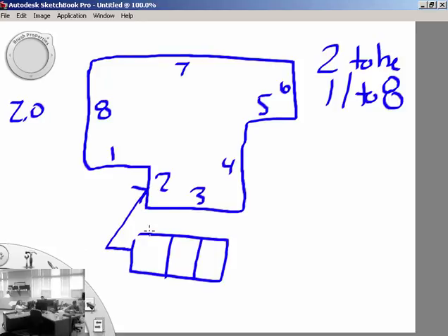Okay, so walk me through this. I need to establish that surface 2 is parallel to surface 8. So what's one of the first things I should probably do to get this set up? Establish the datum, right? We'll go ahead and establish our datum. So we'll do this symbol, right? This is our datum reference, correct? So do you agree that I put it in the right place?